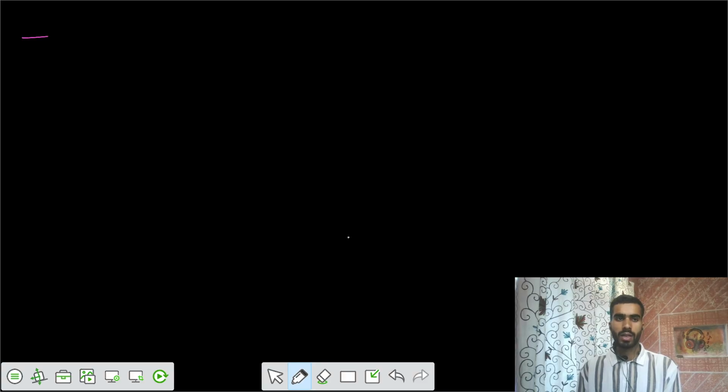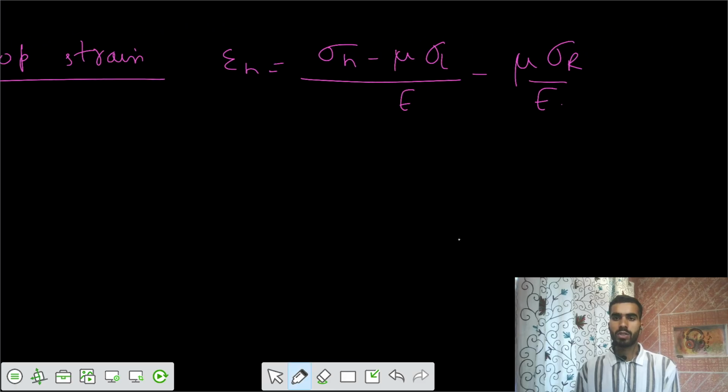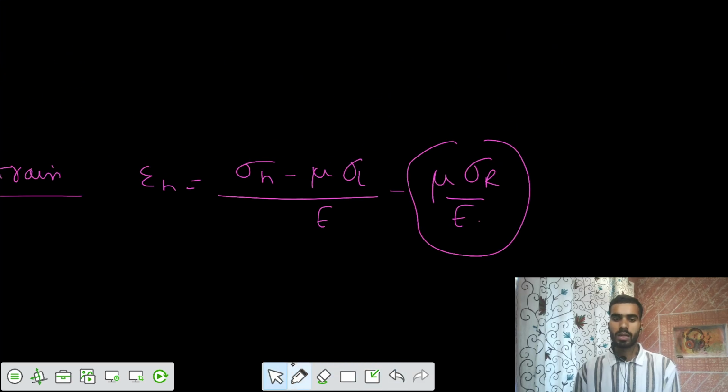Let's take the strain we call hoop strain. The hoop strain we can write as epsilon H equals sigma hoop minus mu times sigma long by E, minus mu sigma radial by E. One thing is that we say sigma radial is negligible with respect to these other two values.